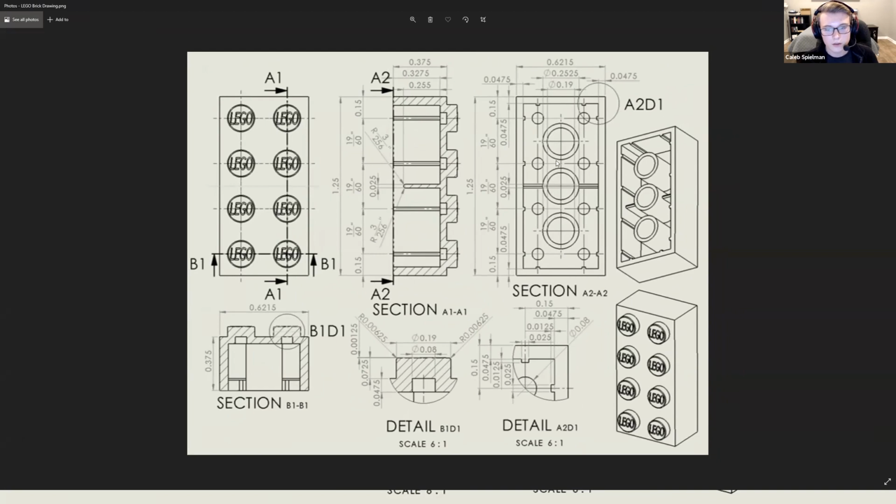All right, so here, if we look at the drawing file, we can tell that ignoring the circles, this part, section A2, which is here on the right, is what we just made. This face is what we have just sketched. So now let's go to a different view and try to find a value that gives us the height of that solid. So here we have the arrows indicating endpoints of dimensions. In this case, it is 0.375.